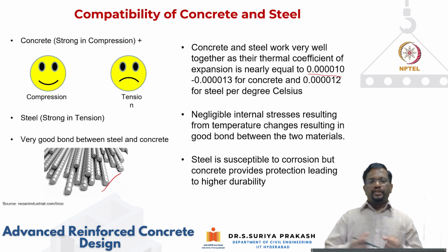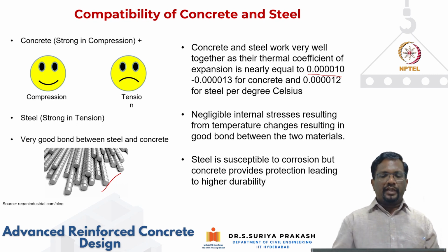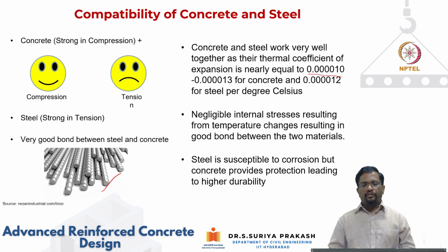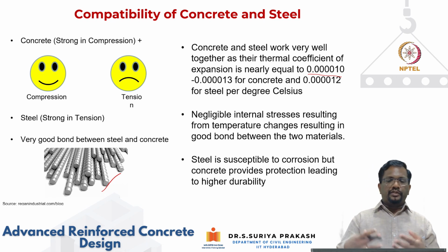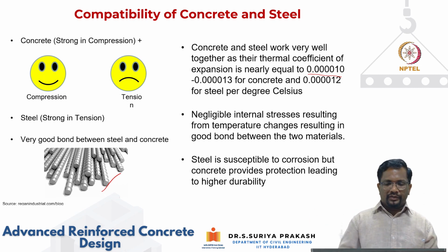So, there are no residual stresses that are going to develop because even if it is a temperature effect, they're going to expand by more or less the same amount. So you end up with negligible internal stresses resulting from temperature changes. So that results in very good bond between these two materials. That is why several structures are standing for more than 100 to 200 years, right?